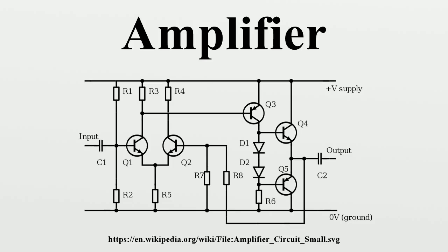Transistor amplifiers. The essential role of this active element is to magnify an input signal to yield a significantly larger output signal. The amount of magnification is determined by the external circuit design as well as the active device. Many common active devices in transistor amplifiers are bipolar junction transistors and metal oxide semiconductor field effect transistors. Applications are numerous. Some common examples are audio amplifiers in a home stereo or power system, RF high power generation for semiconductor equipment, to RF and microwave applications such as radio transmitters.